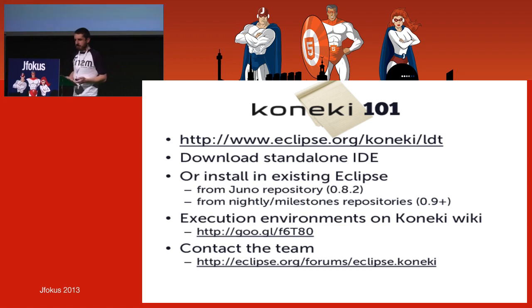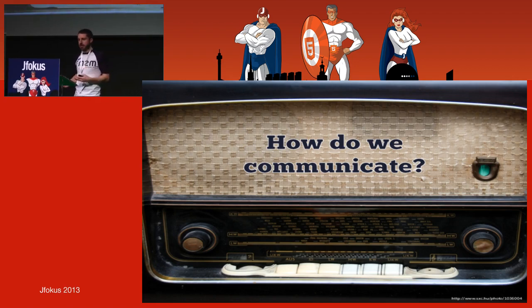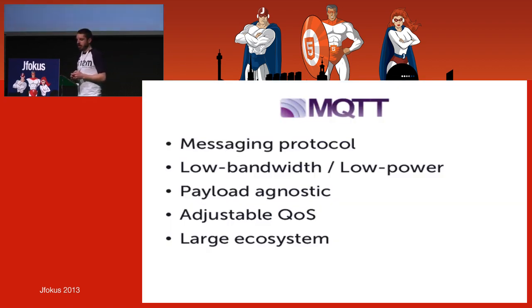So yeah, we want to start building the solution using Lua. Now we are going to need, at some point, some communications between the embedded device and the server. And as I said, there are many protocols for communicating back and forth with the server. One we think is quite interesting is called MQTT, for Message Queue Telemetry Transport. It's a messaging protocol invented in order to have a way to transmit data in a very low bandwidth and low power way, with a publish-subscribe mechanism.